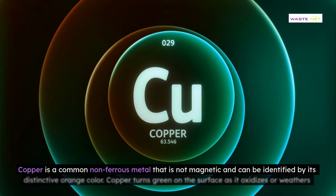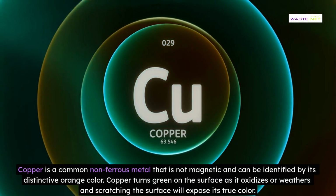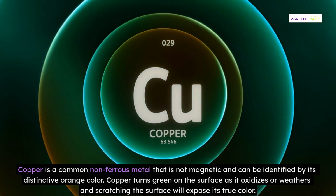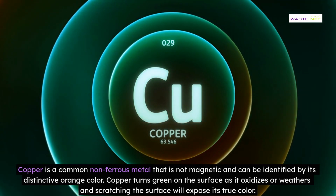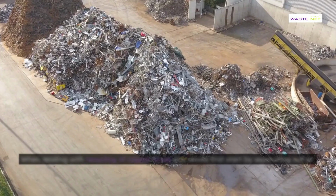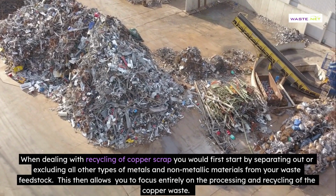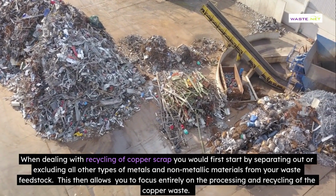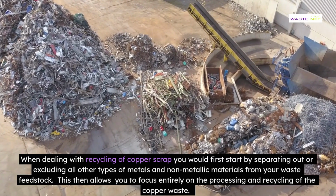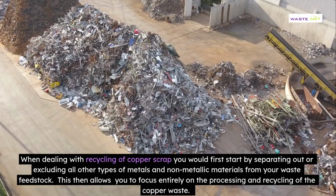Copper is a common non-ferrous metal that is not magnetic and can be identified by its distinctive orange color. Copper turns green on the surface as it oxidizes or weathers, and scratching the surface will expose its true color. When dealing with recycling of copper scrap, you would first start by separating out or excluding all other types of metals and non-metallic materials from your waste feedstock.